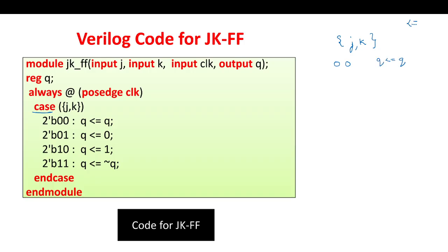And this is called the non-blocking assignment, which is commonly used in sequential circuits. And if it is combinational, then we will use this one, which is blocking.